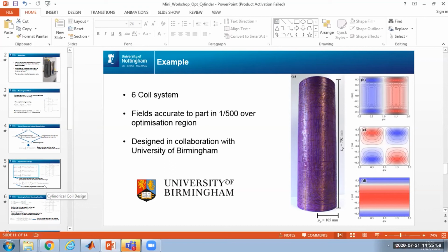So long as the holes in your end cap are sufficiently small, they don't affect the measurement or the optimization in any meaningful way. You can still design magnetic fields that are homogeneous to 1 part in 1,000 over your optimization region, which is about half the length of the magnetic shield, with those end caps in there, and it'd be perfectly fine. If anything, the only thing it's going to hurt is your ability to shield magnetic fields.